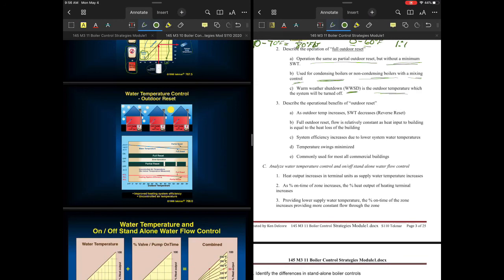People that have in-floor heating in their basement and are running water temps that are too high will have higher heat losses through that floor than they should. So if you can control that system to the least amount of energy, you will benefit. If we can lower the water temp in those in-floor heating jobs to the least that you need, you're going to benefit from an efficiency gain.